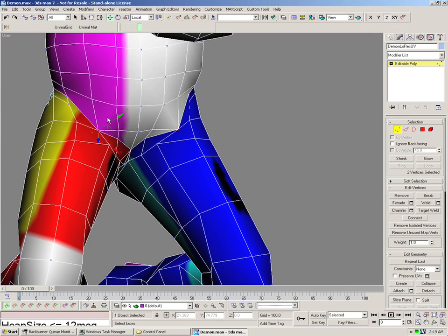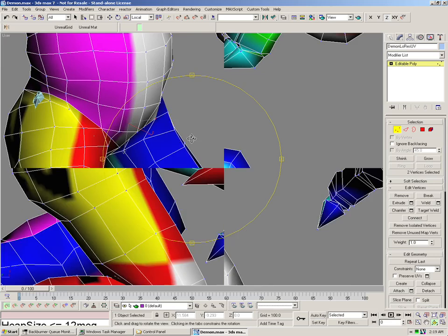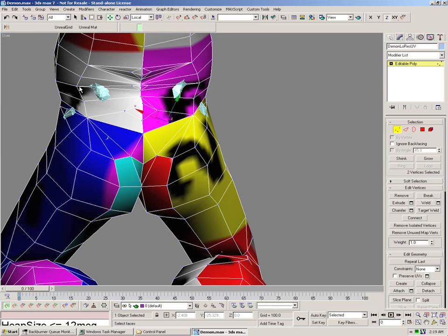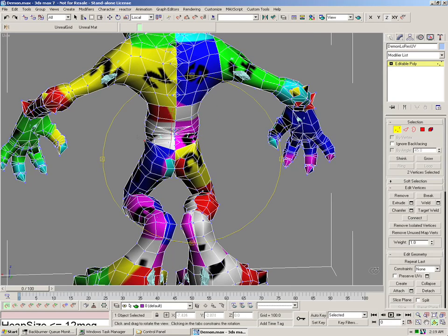Go back to local. Also, if you're working in local space, when you're in sub-object mode, especially on the vertices, essentially that's going to move that vertex straight out along normal to the surface. That's kind of a handy way of pushing out vertices. So you can see I can pretty quickly just come in here and symmetrically pull this stuff out. I'm just trying to include that surface underneath so that I don't have any surface intersections. So that's kind of the process for that.